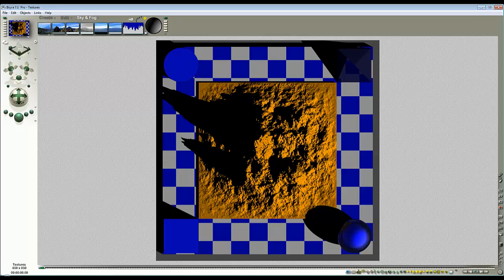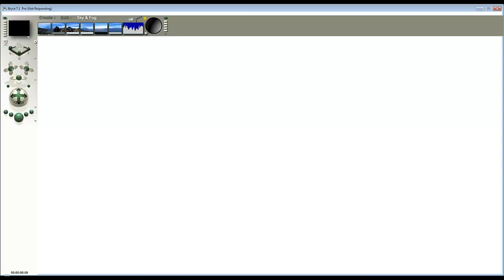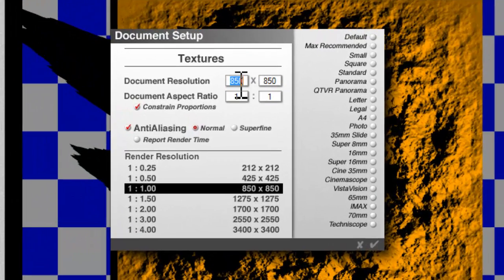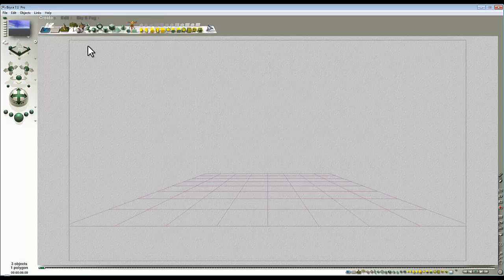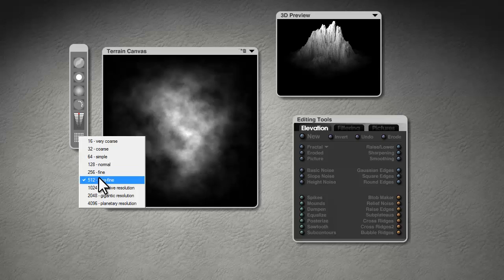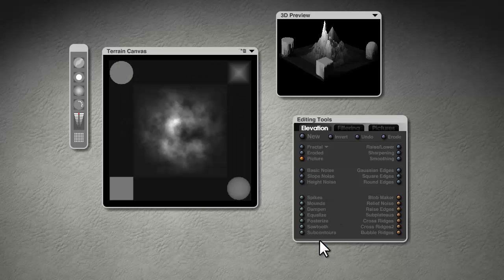textures. Right, I now need to open a separate instance of Bryce and import the terrain height map. It's fairly easy. To optimize this, I've done this at a resolution that coincided with the resolution of the terrain height map. So imagine that at 1024 or 512, because otherwise we're either going to be stretching pixels or losing information. If I just create a default grey terrain by holding the Control key down and clicking on terrain and edit, you see this set resolution is 512. So if we load in, use picture, load in the height map that's been created here,